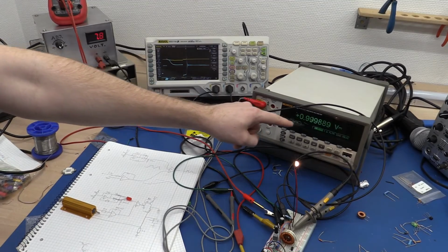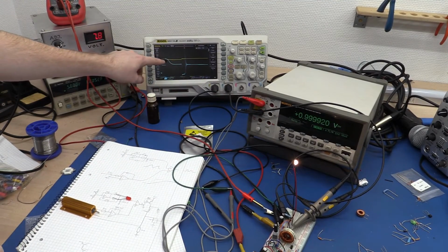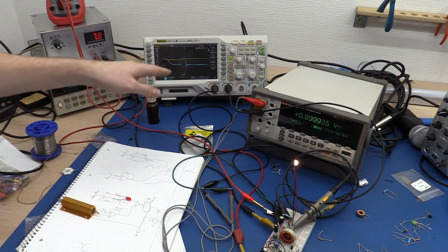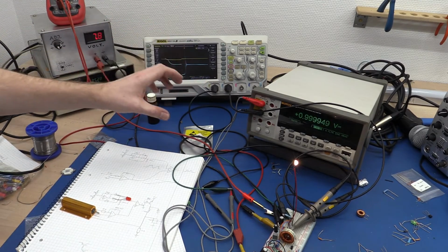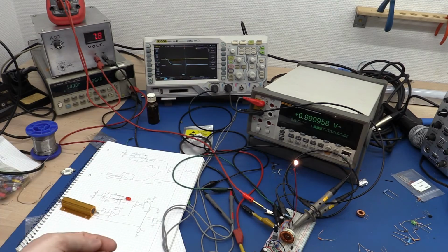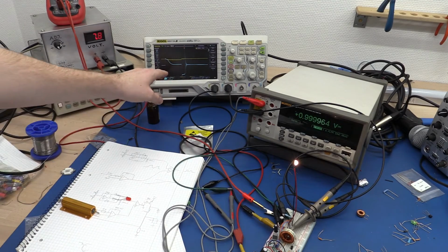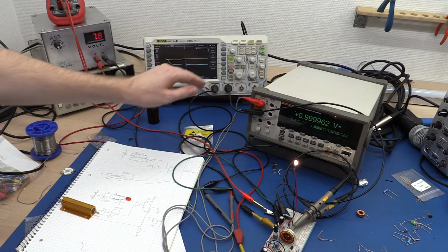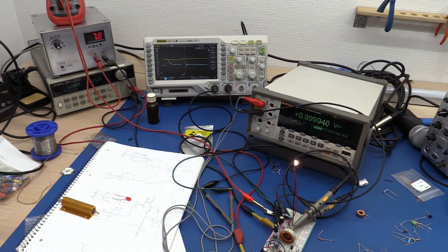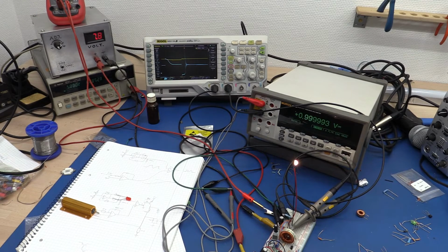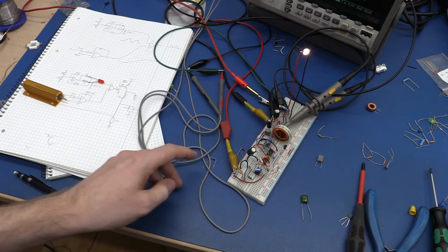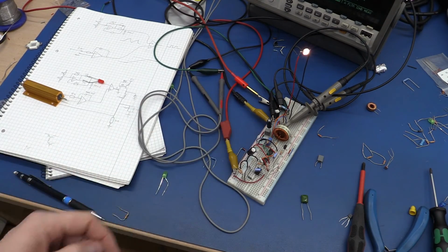Around 100 milliamp we really start to punish this poor transistor here. Because it's a switch mode supply, it needs to conduct more when we're charging up the inductor, and this poor little transistor simply cannot do that. It's not spec'd for it, so if we wanted to do that we needed a bigger transistor. So I think that's it for our homemade regulator here.